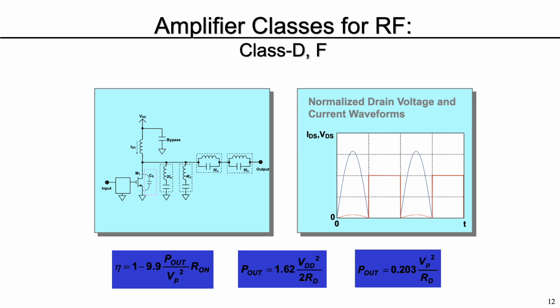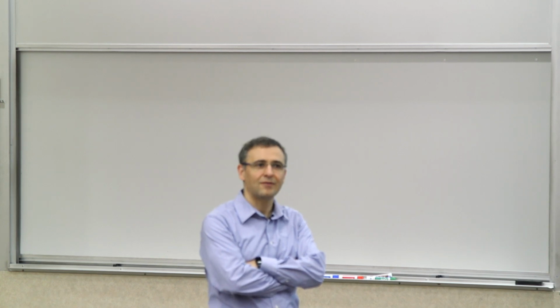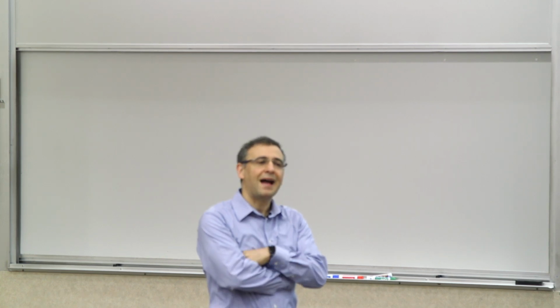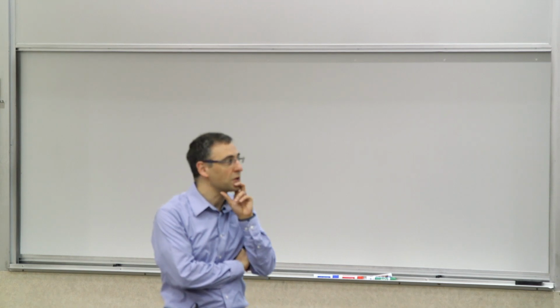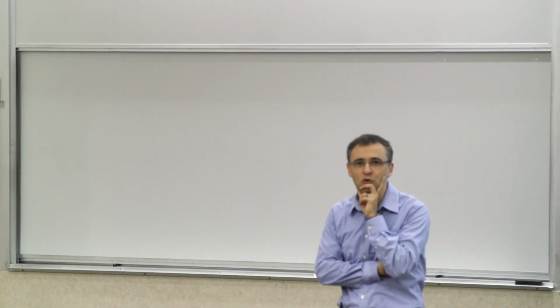And the parallel ones, that's 3F0 and 5F0, are going to be open circuited at those particular frequencies. So you're short circuiting at the even harmonics. What does this do, if you think about it? They would affect the voltage and current at even and odd harmonics. Now, forget about this for a second, and imagine that you wanted to create a voltage waveform that was a square wave. What would you do?